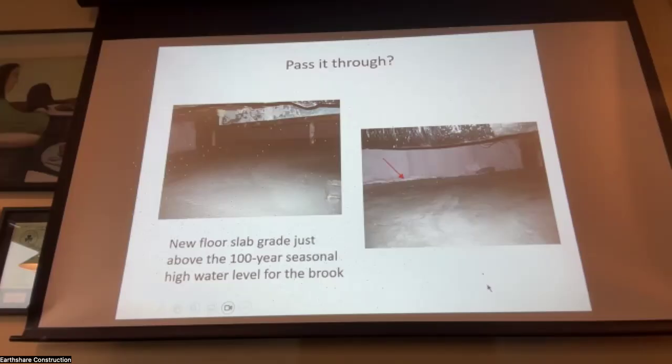What's your threshold on the humidity in spaces? I would say 60%, 70%. Well, the recommended healthy relative humidity for buildings is 40 to 60. So that's just at the top of the healthy range. I'm just telling you what the health industry says.